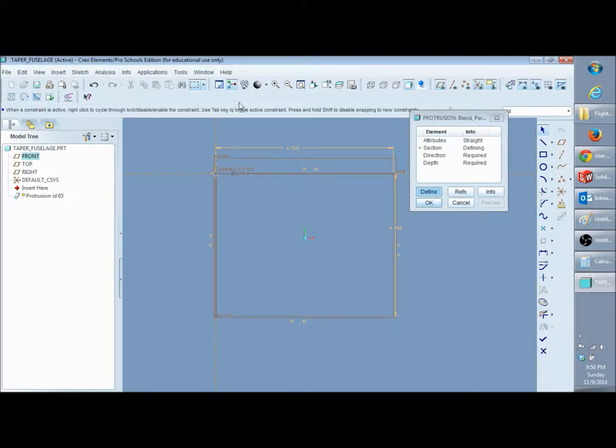And Creo is pretty awesome because it'll do all the math that it takes to taper down to that shape. It'll do all the math for you. Okay, so go ahead, just do a square. I want the back surface to be about 4 inches. Wait, no, that's too big. 2 inches.